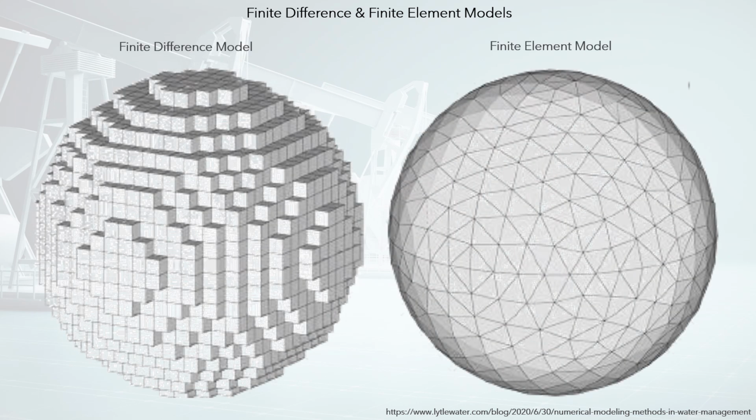The finite element model, FEM, consists of a mesh with irregular triangular (2D) or quadrilateral (3D) elements. An element in a mesh of a finite element model can be compared to a cell in a grid of a finite difference model. Different than a FDM model, in a FEM model calculations are carried out on the nodes, which are the vertices of each element. Due to the flexibility of a mesh, the model can represent the exact geometry of an irregular model shape. Furthermore, the discretization can be refined locally, around the area of interest. This approach can achieve higher accuracy, in exchange for higher computational effort.